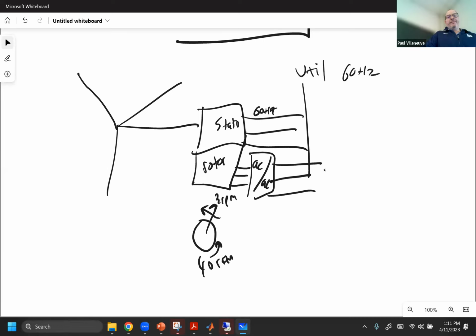Yep. For these systems. So I was just wondering if for induction motors, since there's no magnetic field, even though you've shorted everything, there's still no permanent magnet. If you don't have any current running through it. Right. Once you have no current running through, you have no rotating magnetic fields. So it's just a hunk of iron rotating in a field. Right. Okay. Thanks. There's nothing there. And that's one of the biggest problems with wind turbines. If I have a fault out here on the wind turbine bus where that connects, what happens?